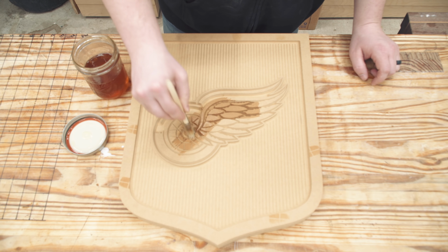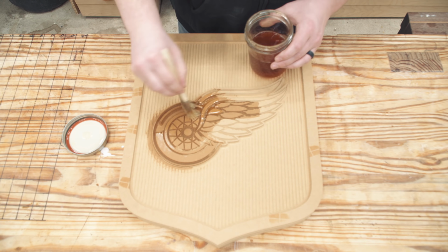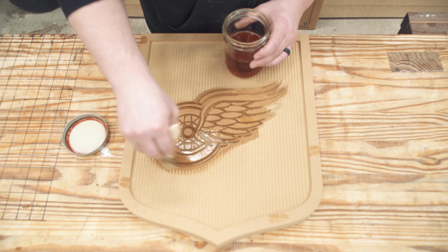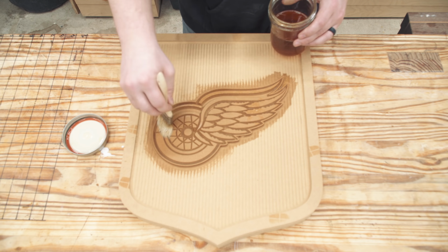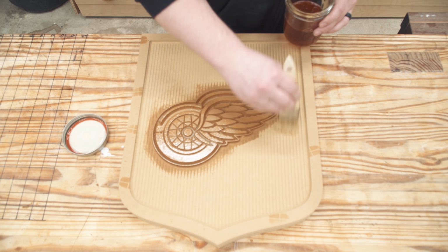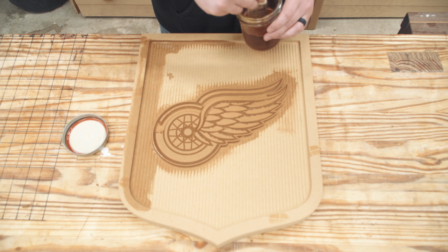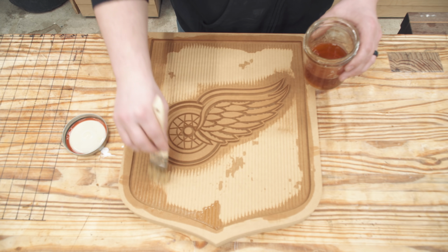And now the sign can be sealed with a few flood coats of shellac based upon my research. So I've never used MDF outside in a sign like this, but I've researched and found several established sign makers who have had good long-term results using MDF sealed with shellac and then finished with an outdoor rated finish. Like I said, I've never done it before, but I'm going to take their experience and run with it.